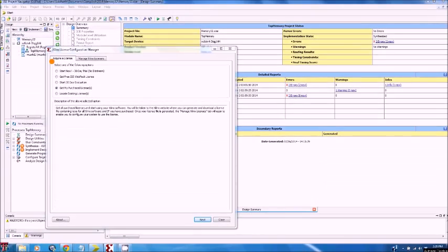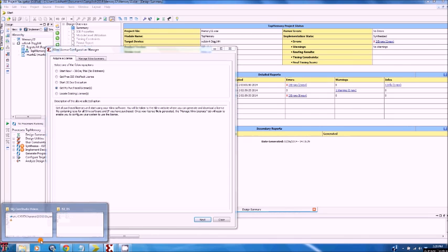Once you've completed the installation process, you'll be prompted to add a license file. In order to do this, you will need to go to your email address and download the license file from the Xilinx email. You will need to save this file under the licenses folder. You should be able to find this folder in your main Xilinx folder under Common.